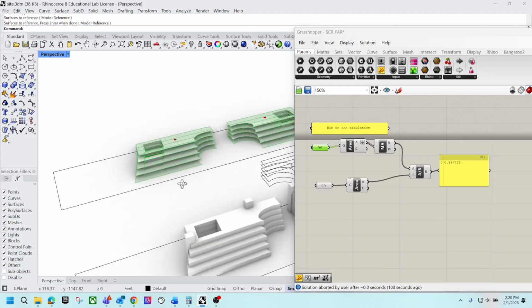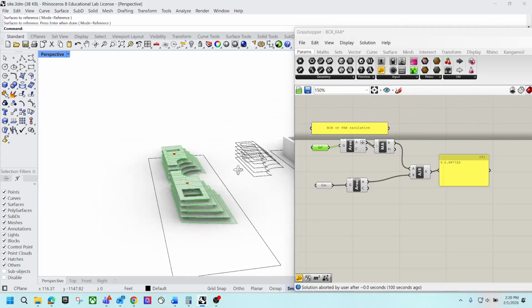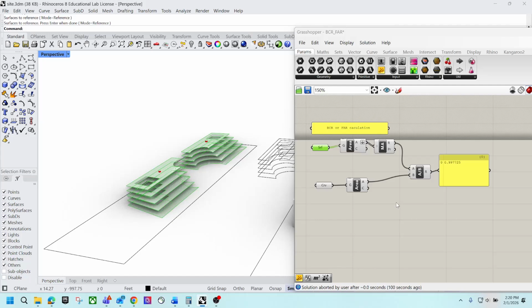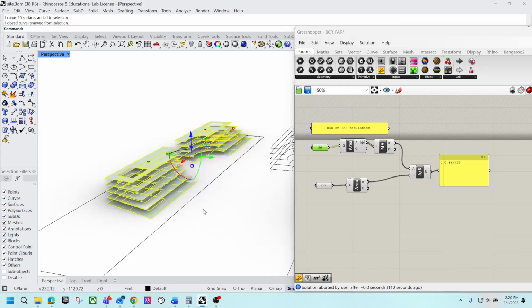All right. Yeah, I think that's pretty much the whole logic using Grasshopper. You can definitely reconfirm by just using area. So here, if I select these floor slabs and type area, you have this value. Then I use a piece of paper, write it down, calculate the square foot of the total site, and then I can manually calculate.